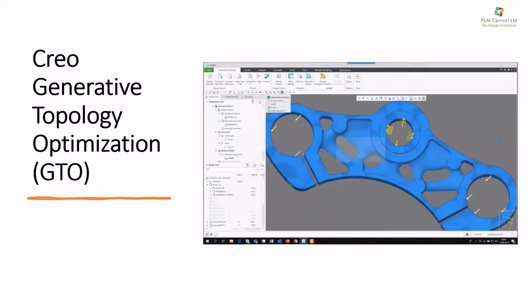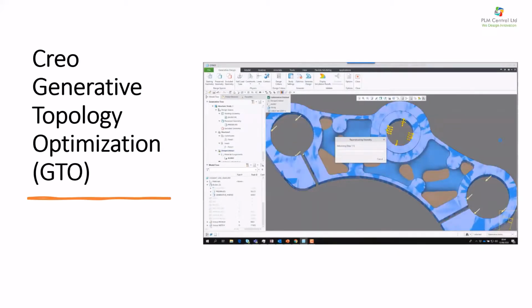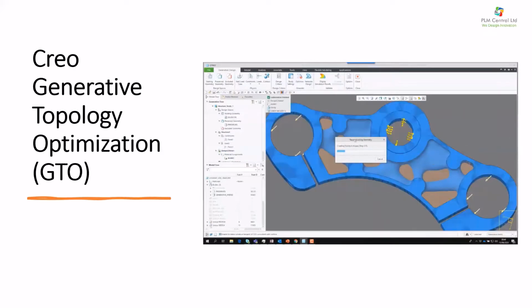version of the BREP model, and what it will do now is take that tessellated information and intersect it with all of the retained and preserved areas such that we get a series of curves, and you can see those being generated now. It says creating style curves, and here they are, the intersections between the retained and the generated shape. Once it's done that, it will then start to create the freestyle shapes.